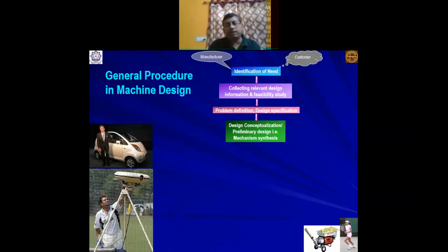Now the very first step in any machine design problem or any product development problem is to make a conceptual design, where you have to synthesize your mechanism. Now, as you can realize, think about which way you can throw the ball. One might be, from the mechanical engineering point of view, a spring-loaded thing. You might have seen in a fair that bullets are thrown by a spring-loaded gun. So using the spring-loaded gun, you can throw the ball. This might be a possible mechanism.